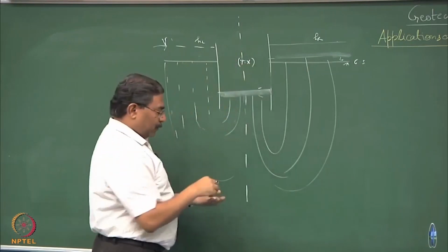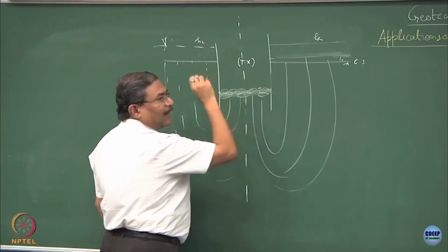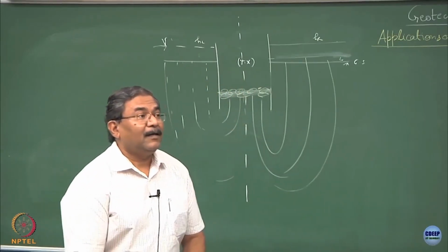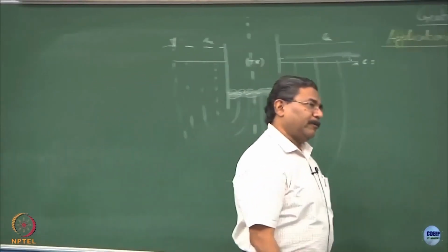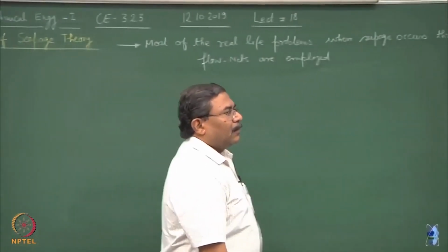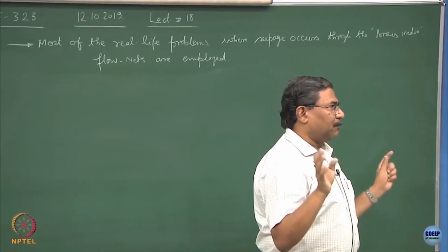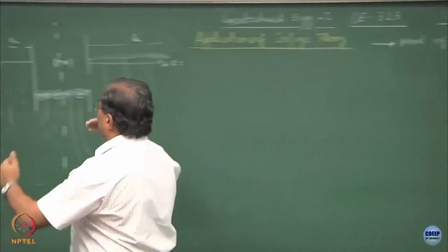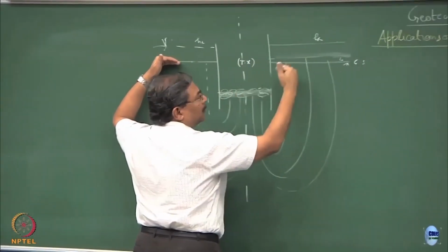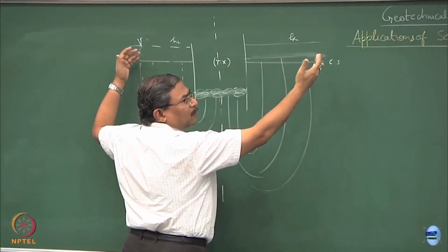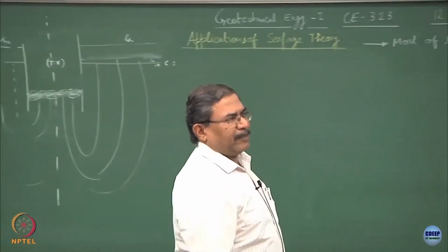What he was talking about, suppose if I put a filter layer over here and I objected, why? I said whatever you are holding over here, it will keep on seeping out, I do not get any advantage out of it, fine. So, I am sure you are getting different dimensions of the situations. Is this part clear? Yeah, so just go by this fact. This is equipotential number 1, this is equipotential number 2, this will be equipotential number 3. I do not know what the equipotentials over there are. So, what you have done is you have created a situation which is case specific.